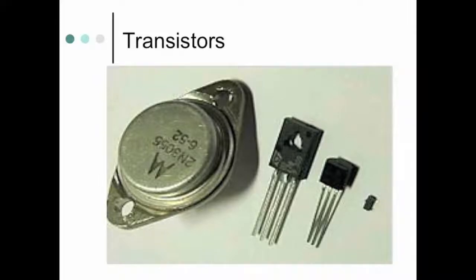The one on the left, the 2N3055, is a power transistor, and then these are other transistors, and they get pretty hot. So the metal casing here has two bolt spots on it, and it's usually bolted to a big piece of metal with fins on it so that air can cool it. It's called a heat sink. So it takes the heat that's generated inside of this little device and it radiates it so it doesn't overheat and blow up.